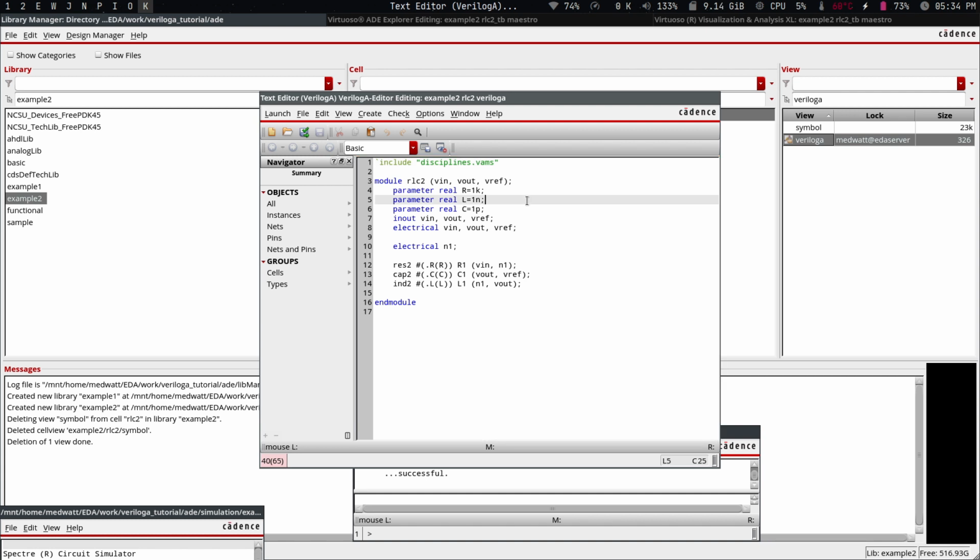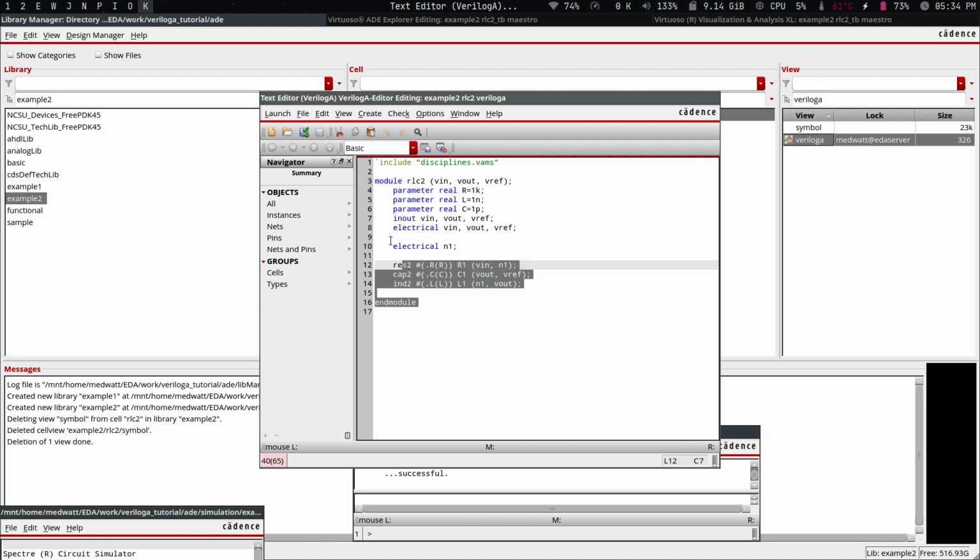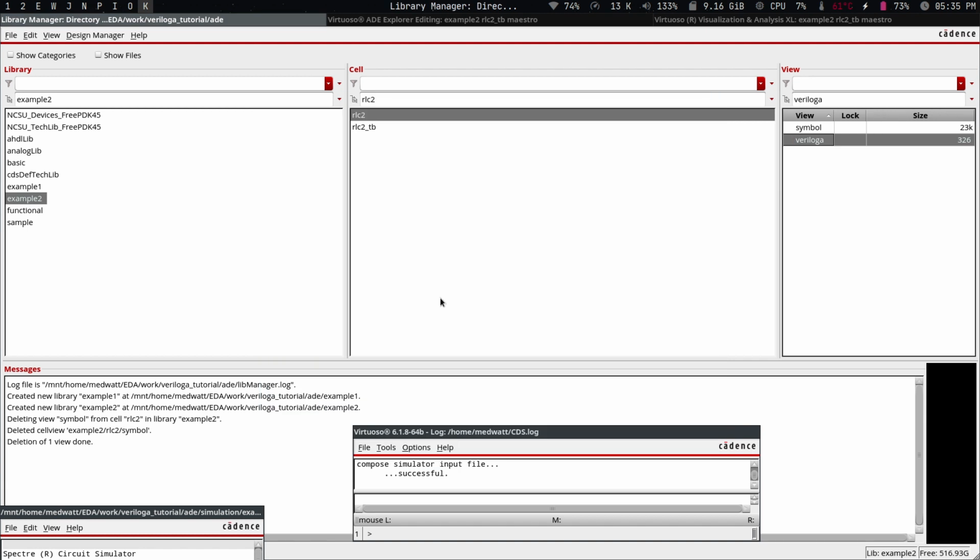If you want to use some modules that you get online from somewhere, defined in different blocks, you don't need to go through some jujitsu to stitch them together inside the ADE. You can just paste the top module here, reference the other modules inside a file like this one, include it during the simulation, and you're done.